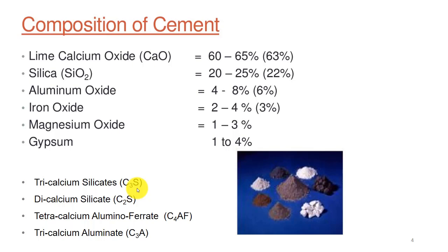Secondly, the dicalcium silicate contributes toward the hydration reaction at later ages, like above 50 days or more. When you have a concrete at more than 28 days, the strength gain in that concrete would be due to this component, that is dicalcium silicate.